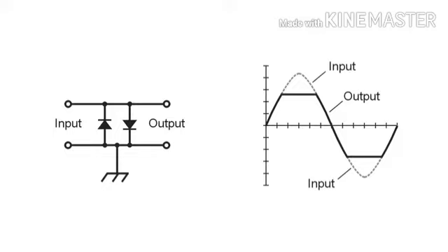Unfortunately, if a voice signal is applied to this input and the voltage exceeds this forward breakover voltage here, clipping on a voice signal will produce distortion that can get so bad that you can scarcely even understand the voice. So this is what you would use in an old-fashioned receiver without any automatic level control if you're listening to CW. They used to use it, CW meaning continuous waves or Morse code signals.